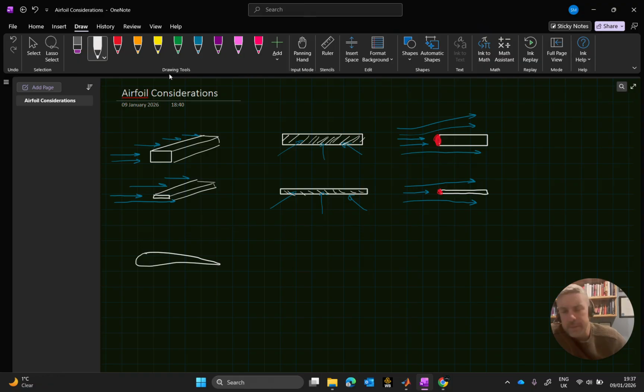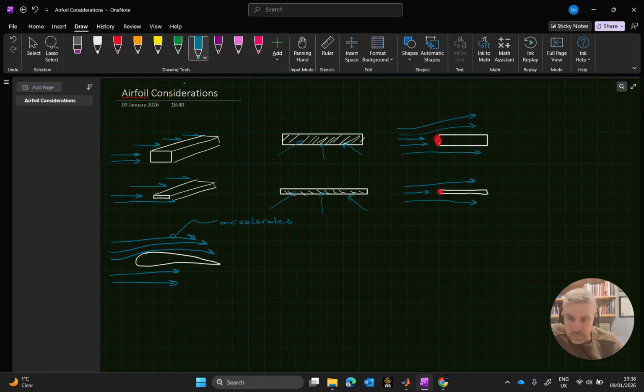So a lot of people, I think most, will always talk about Bernoulli principles first, because it gives a better explanation of why airfoil surfaces are curved. And the reason is that when you're coming over a curved surface, this flow here accelerates. So I'm going to keep this short because we could do other videos and talk about this for hours. The curved flow comes up and then accelerates over that.